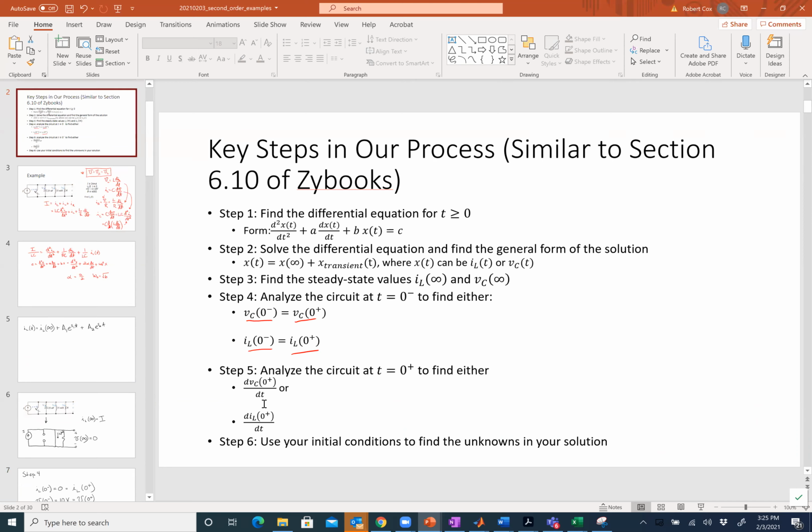Okay, thank you. That's the key thing, because we talked about it. We gave a physical reason for that, which is to say energy has to always be continuous. So if that has to be continuous, then the energy storage variables have to be continuous. In words, what this means is that voltage is always continuous. It can't have a jump. I can't go suddenly from 4 volts to 5 volts on a capacitor. That can't happen suddenly. Would that be the same thing for VOC and V infinity as well, right?